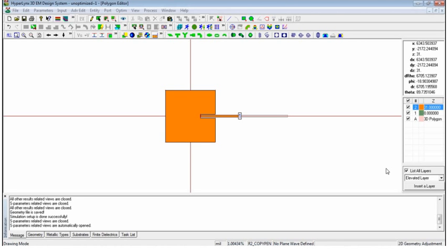In this case, we have defined only 2 variables, because it's a pretty easy structure, a microstrip, which has only 2 parameters to control the resonance. One is the length and one is the insert depth. So this is how optimization works in IE3D.